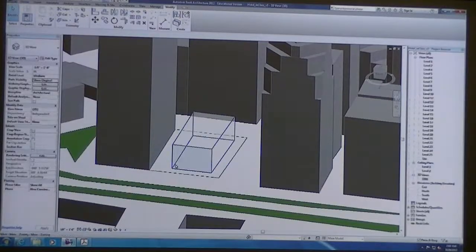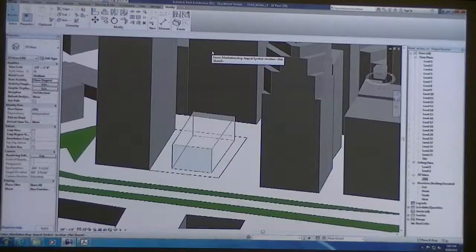If you just click your line, so I selected all 4 lines around my site, and I selected the area and then did create form. That'll make a straight extrusion. Just select create form, select your item and then create form.